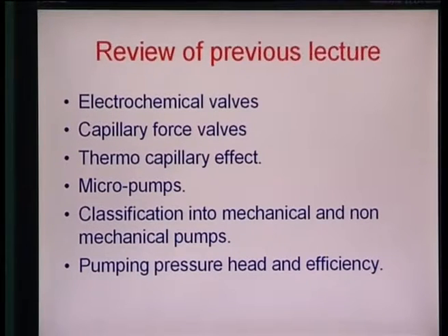Now today we will be starting on designing, and we also talked about in the last lecture a phenomenon related to peristalsis. Peristalsis, as we know, is a motion of travelling contractile waves in a microchannel which causes flow to happen. So we discussed a 3-layer device wherein actuation is done by mechanical means, by moving boundaries with high pressure compressed air flowing in a sequential manner into the blisters, which causes the movement of the fluid underneath it. So the contractile motion is discretized and results in a unidirectional flow within the microchip.